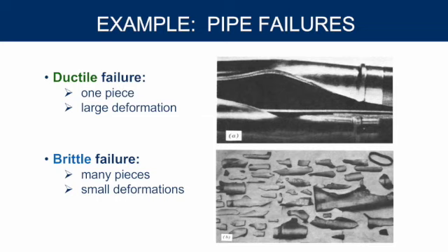All right, so which one do you want? If you have a pipe filled with a toxic gas, you're working at a refinery or some other system, and you're the one that has to go around and make sure everything's working, all the pipes are running, all the valves are open. So if you're walking by for your inspection one day and you see a bulge starting to form in the side of the pipe, that gives you an indication, oh, okay, I can turn this pipe off, I can report it, maybe we can take this piece out, replace it with a new piece, and then turn it back on. No fatalities, no other issues.